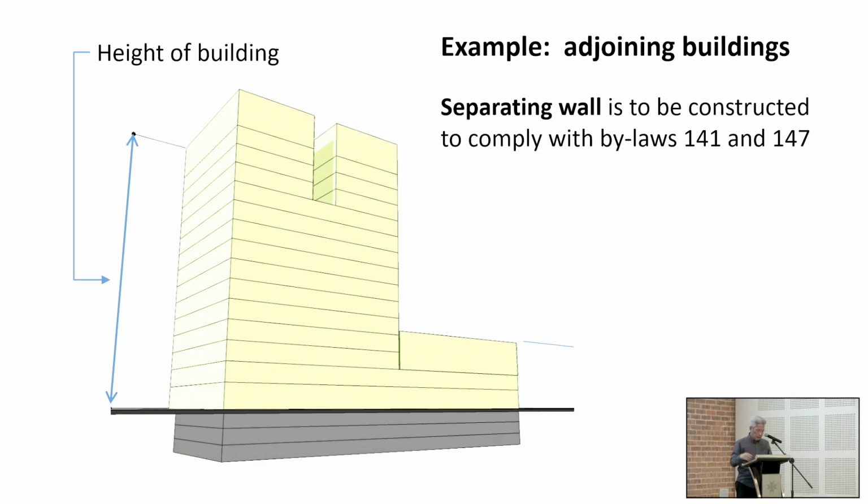So in a building like this, is there a pointer here? Okay, a building like this is one whole building. So if that is the building height, obviously you will require a full firefighting shaft. You will require the fire lift. You require probably a wet riser already with a height like this. So once you have a firefighting shaft and wet risers, there is also the coverage of where you locate the fire lifts, right? What is the radial coverage of the location of a fire lift?